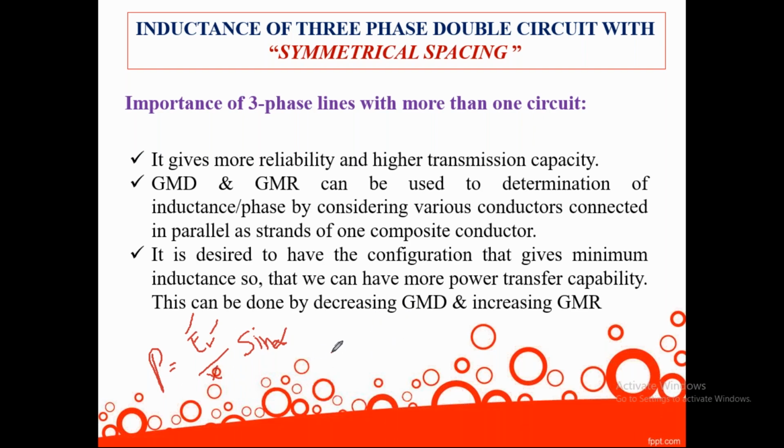Here, power and reactance are inversely proportional. If we reduce the inductance, the reactance value will be reduced. If the reactance value is reduced, the power transfer will be more. Okay, so here this is the power we are transferring from source to load. Okay, now.